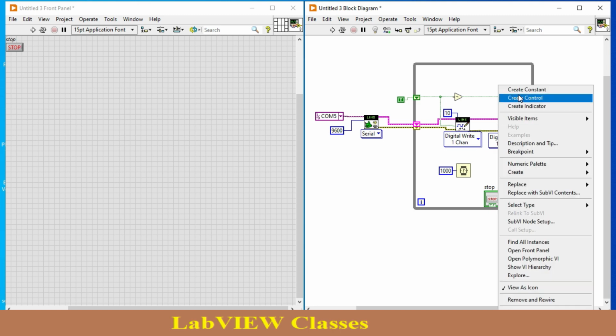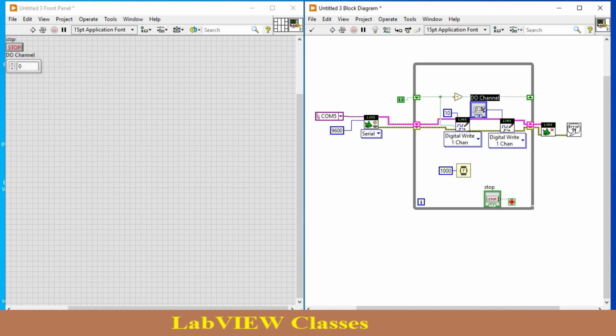Over here you need to set the value of the pin. Let's say I want to generate through pin number 13 in this case, and I need this signal. Right now I have two LEDs, one onboard LED that is connected to pin number 13, and one on pin number 10. When I run it, both the LEDs will blink alternately.